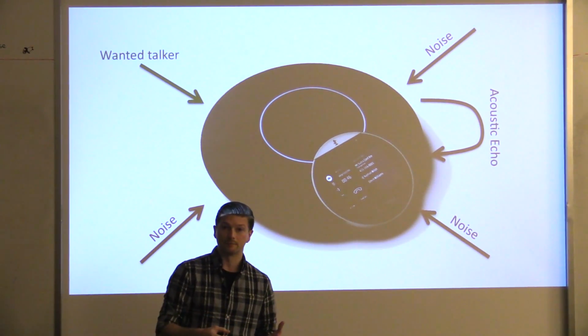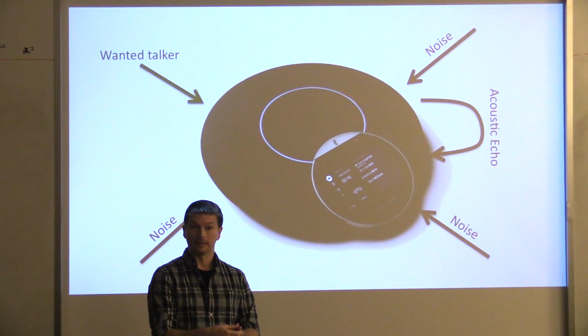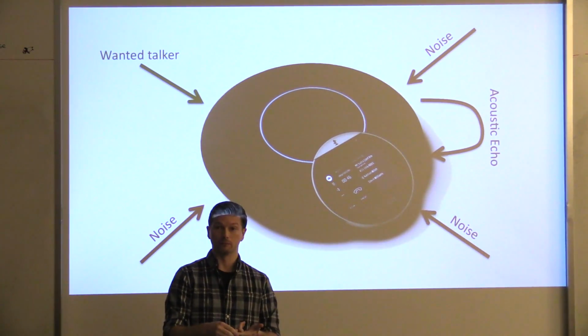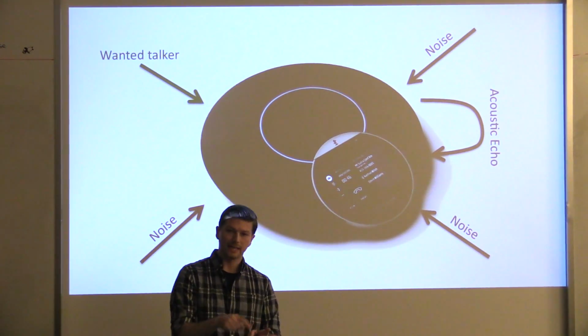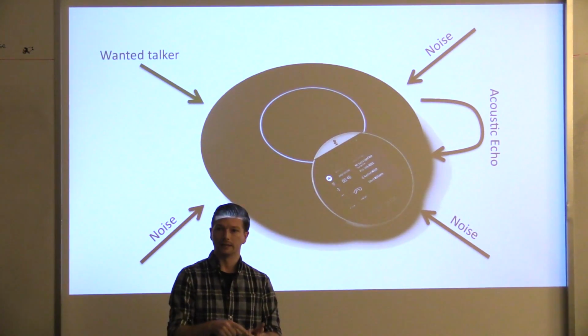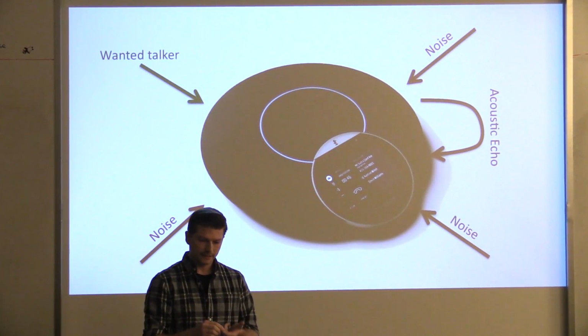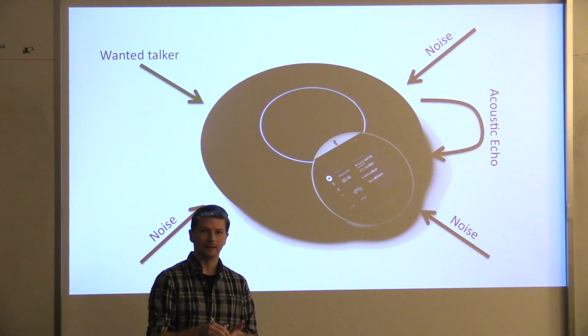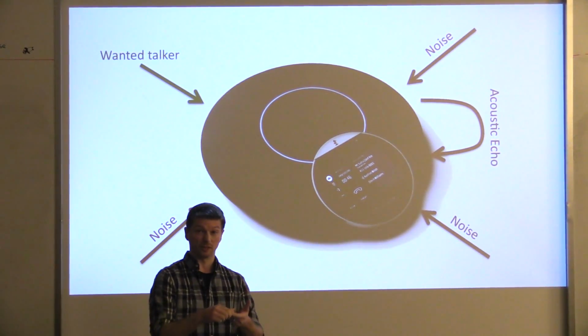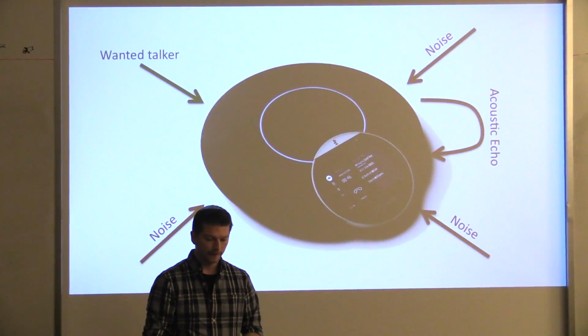This is a kind of supervised problem in that we know the sound that's coming out of the loudspeaker, we know the sound that is being received by the microphone, and we can attempt to estimate the transfer function and then subtract that. So it's a convolutive process, but we have a supervised element to it, so we can actually subtract rather than deconvolve.